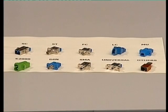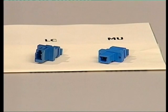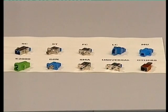Three common connector styles are supplied: SC, ST and FC. Other styles available include the small form factor, LC and MU connectors. These connectors all use a high quality ceramic sleeve, which gives a long and accurate service life. It also avoids metal dust contamination of installed systems, which can cause failures in high-powered fibre systems. The connector adapters are inexpensive, so regular replacement is practical. It is easy to inspect and clean the connector assembly or change a failed through adapter.